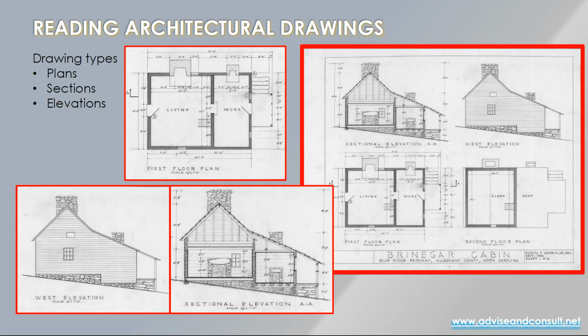And the way that you know that is by looking at the section and the elevation. So the section, it says sectional elevation in the upper left of that sheet, and you can see it enlarged to the left below. The sectional elevation is a slice vertically through the building, and so it cuts through materials, and I'll explain this a bit more shortly, but it cuts through materials and then you see what is beyond. So that's a sectional elevation. A simple straight elevation is just as if you were standing in front of the building and looking at a side of it.